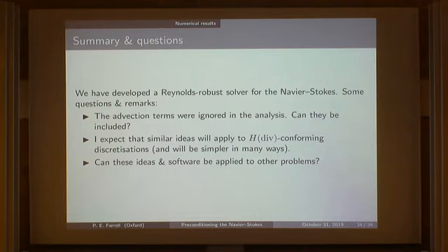Yeah. So the reviewers actually asked us to do that when we submitted the manuscript in the low order case. And so we went and did the experiment. So we implemented another scheme called SIMPLE, which is very popular in the engineering CFD community. And I'm very pleased to say that actually even at low Reynolds numbers, we're much faster than SIMPLE, because they take many iterations. The iterations are much cheaper than ours, but because they're taking so many, it ends up costing more in runtime. And we really did go all out and try to optimize the implementation of SIMPLE. I think it's a fair comparison.